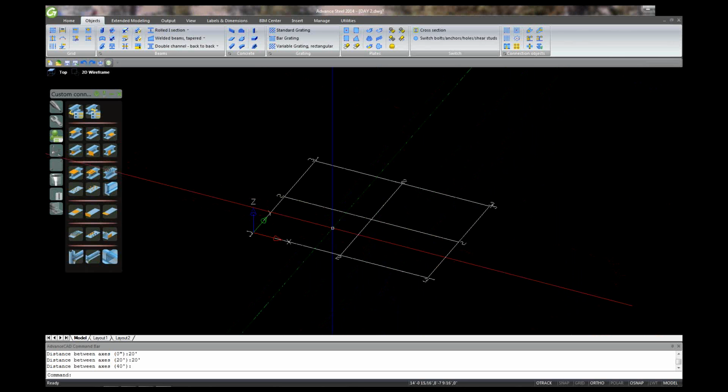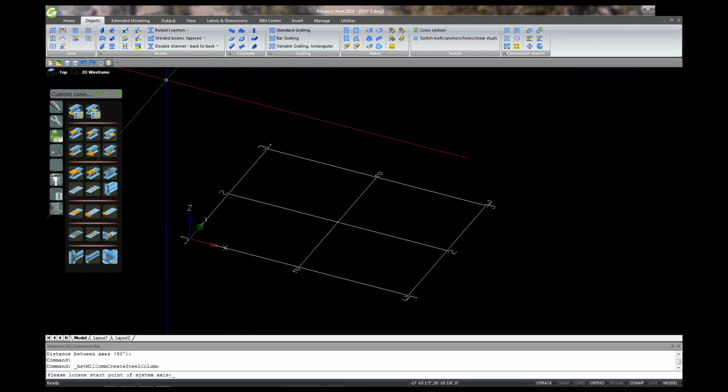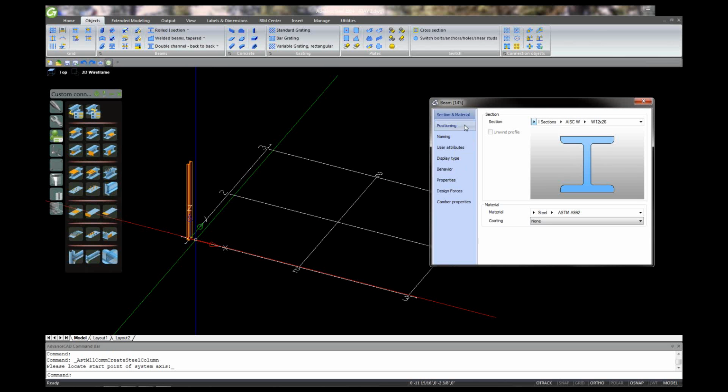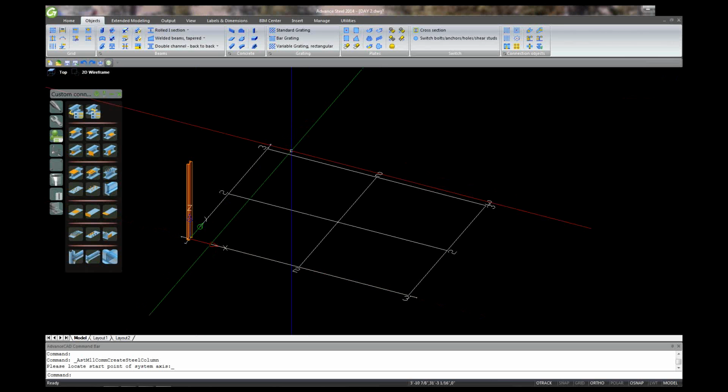Sorry. No, that's fine. So I had to go to the column now. Yeah, go to column and put on the column. It's better if you use the role section because you can specify the column height off the bat. I guess I go to properties there and change that. Yeah, you cannot change here. I can't. Okay. You need to take the beam, take the column, and use those grips.